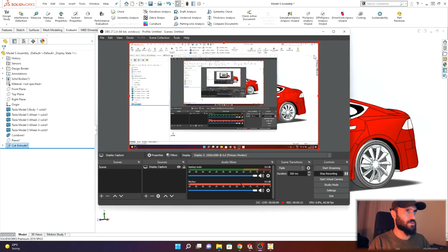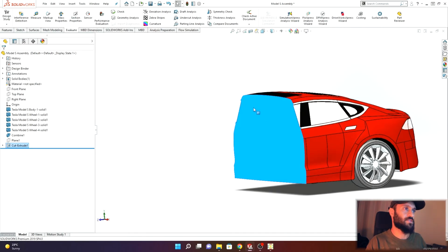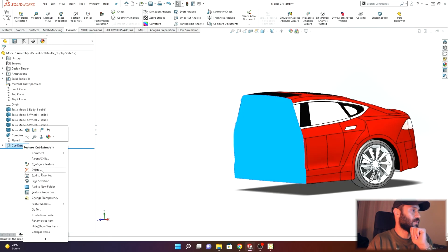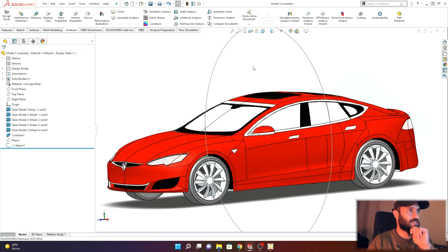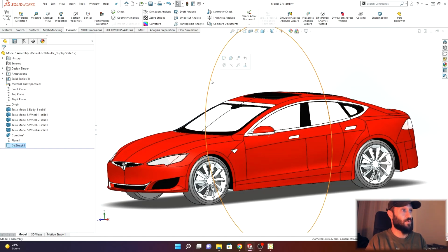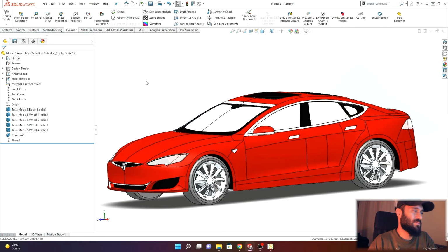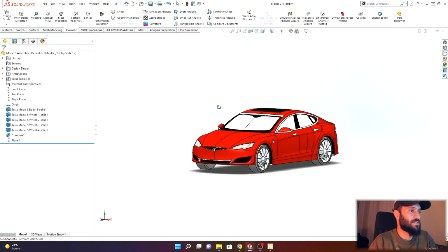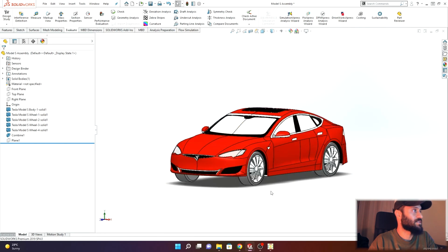Just make sure that when you are getting numbers like this, they do make sense. In this case, 2.2 square meters does make sense for the cross-sectional area because the car is approximately 2 meters wide by 1 meter tall, roughly. It's just good to double check that the values you're getting make sense as you're going along, just to make sure you're not making any kind of mistake.